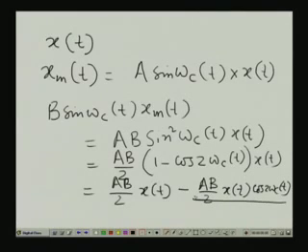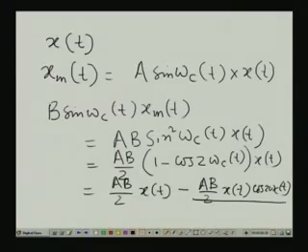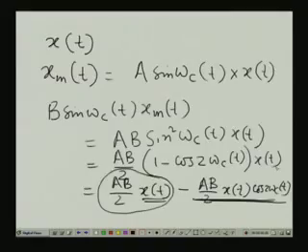Now, suppose x(t) is a low frequency motion signal, about 5 to 10 hertz, and omega_c is let us say 5 kilohertz. So there is a 1000 times separation, and 2 omega_c is 10,000 times. So you naturally see that this will be a 5 to 10 hertz signal, because it is just x(t), while it can be shown easily that this will be a signal whose components stay very close to twice omega_c, of the order of 10 kilohertz.